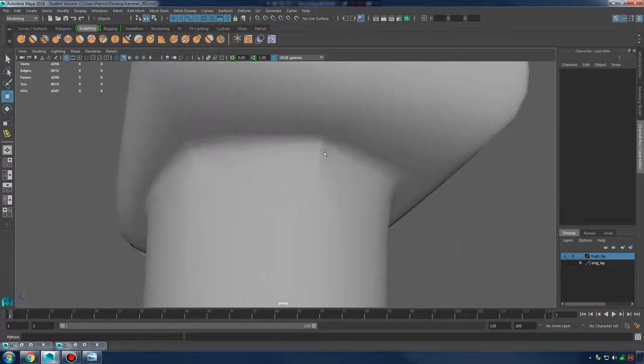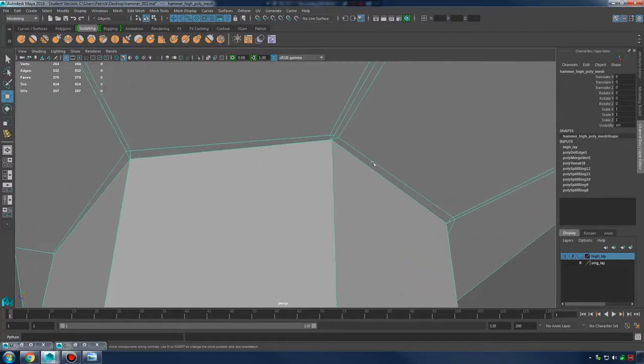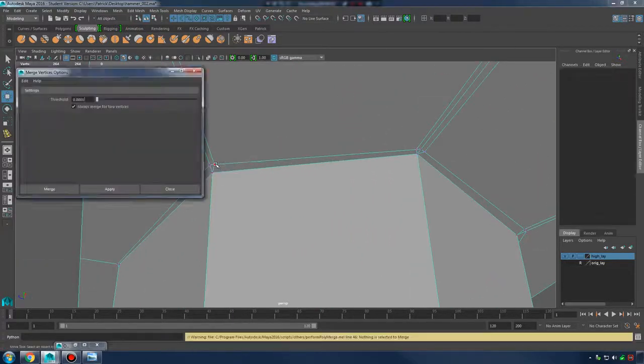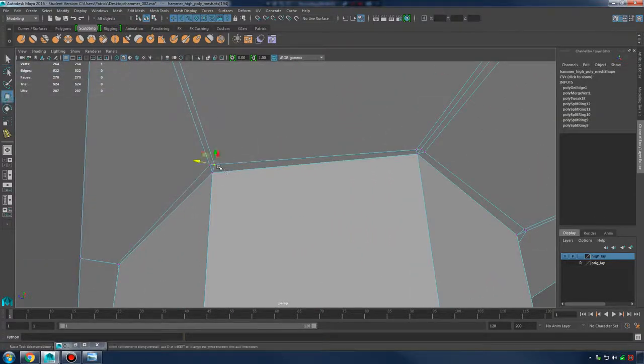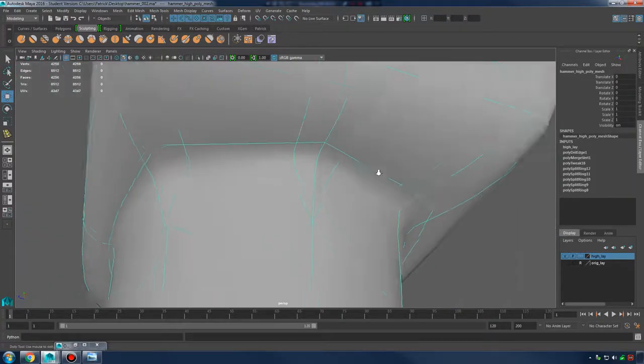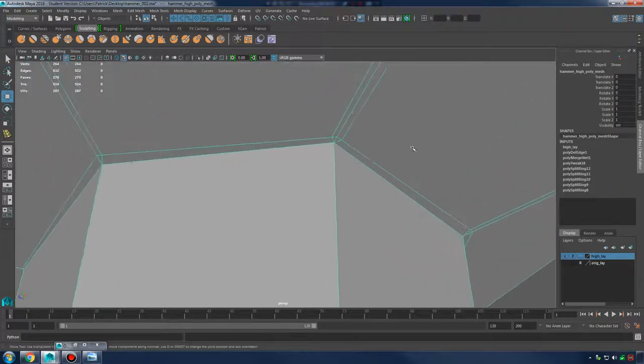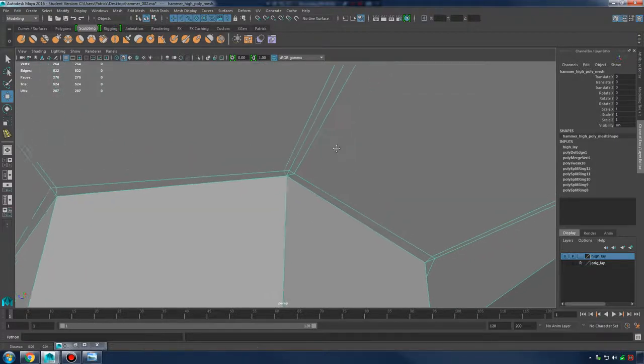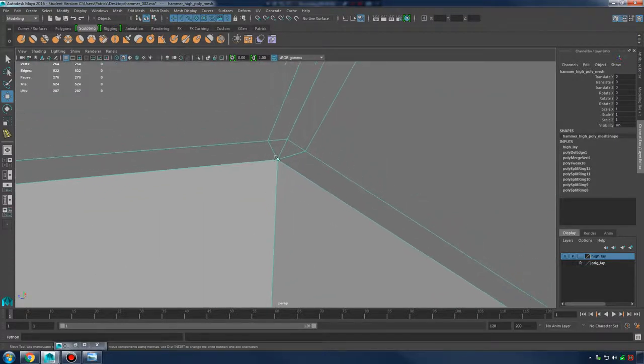But it looks like we're still getting some creasing right there. How are we going to fix that? Well, maybe we need to tie off one more edge loop back, like so. This is a good example to show how poles work, a place where edge loops meet on one vertice, and it's like a crossroads, a fork in the road. I'm traveling down this highway, I get here, and I don't know which way to go.